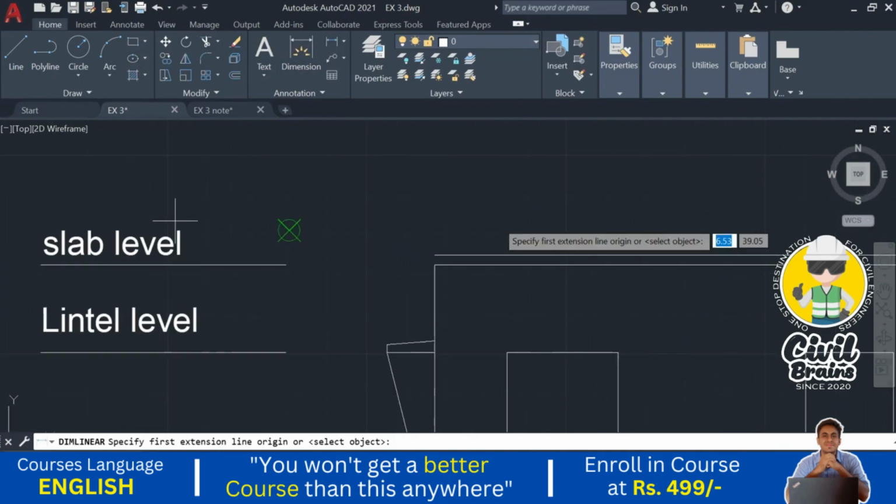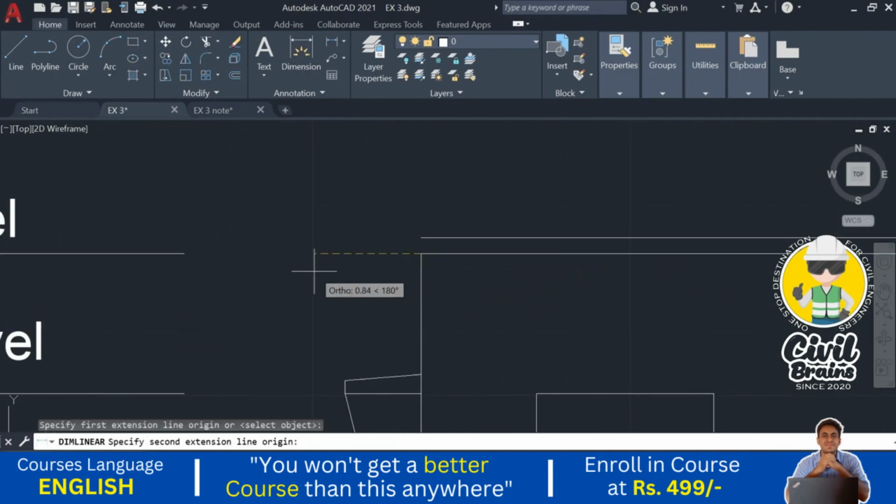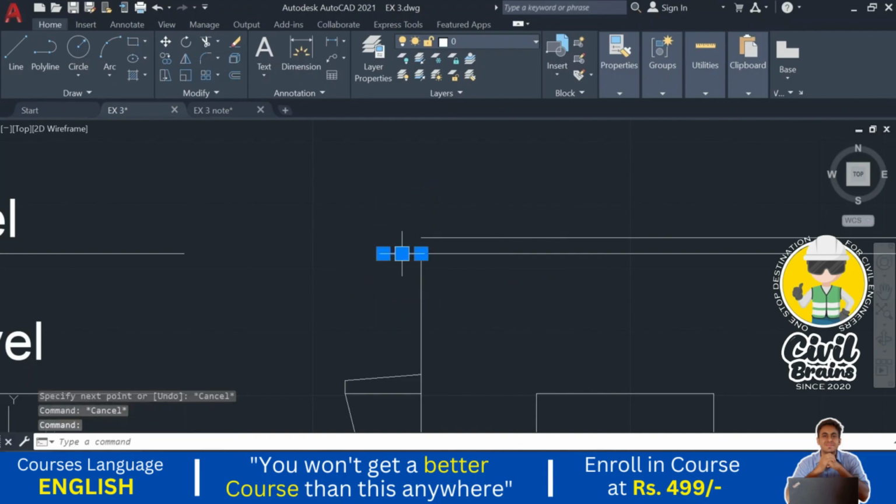So I project this one point. Take the line command, 0.3, not 0.3, 0.45. Slab projection is 0.45. 0.45, press enter. 0.125, press enter. 0.45, press enter.